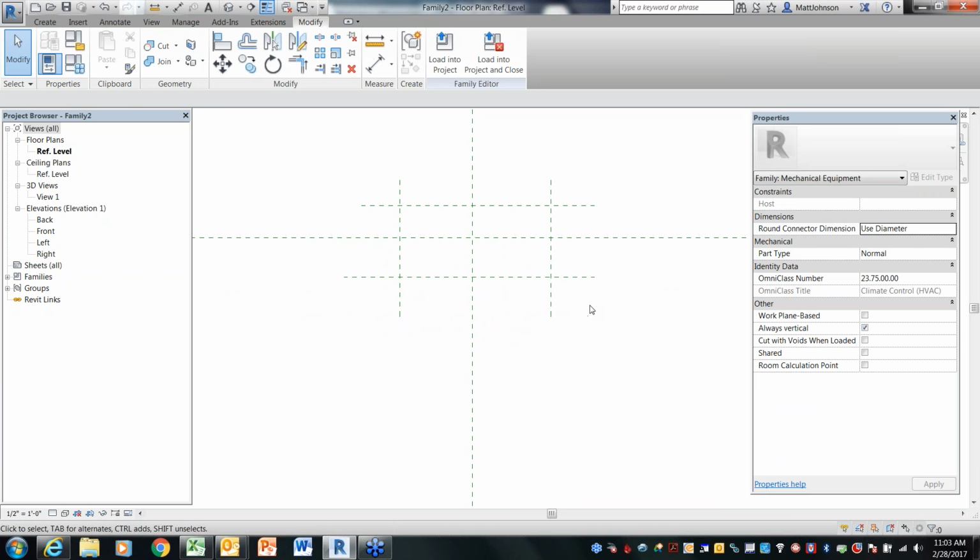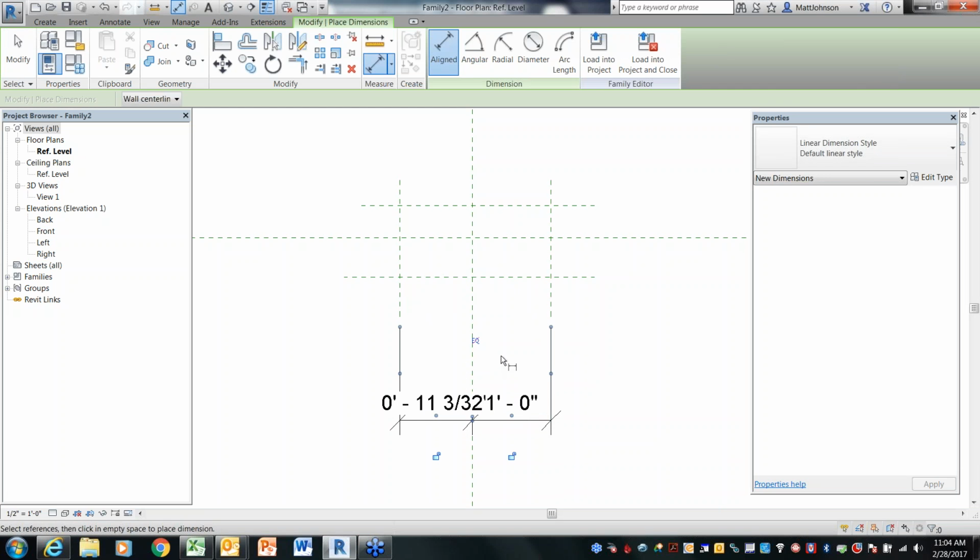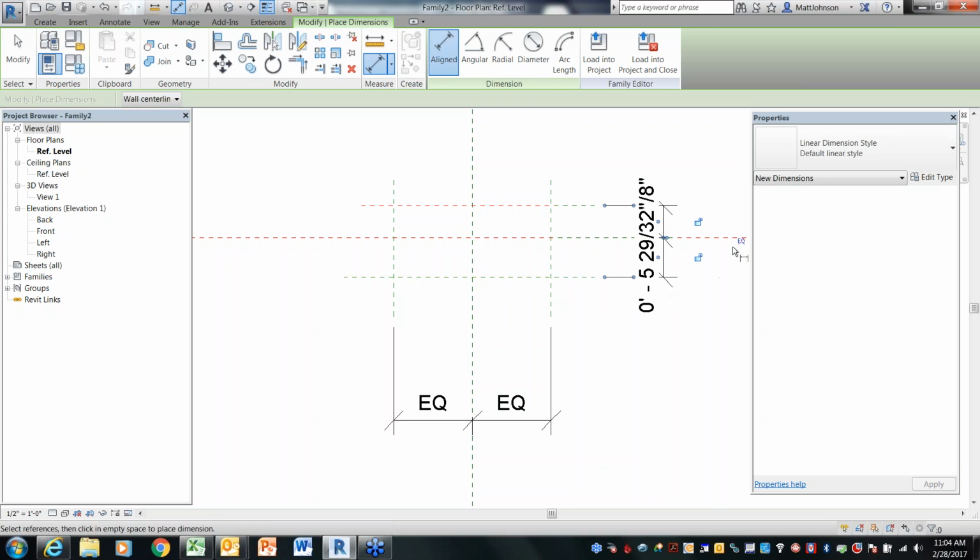And what you want to do while you're placing all of these reference planes in there is get a little equidistant action going so that when you flex the size of the box, it's going to flex from the center out. Okay? So what we want to do is make these 2 equal distance. We're going to do the same thing over here, and just hit the little equal symbol over here. I know it's kind of small.